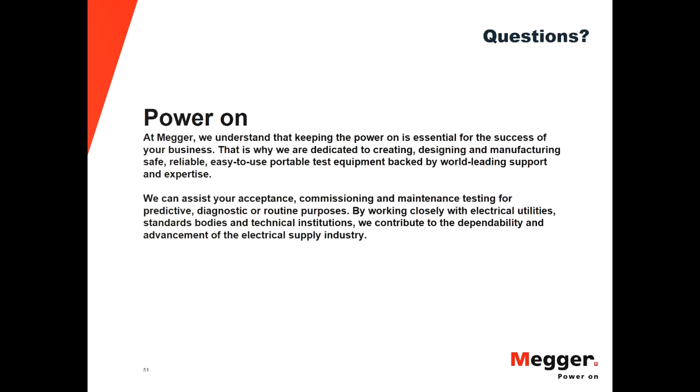Capacity testing requires a lot of effort and time. You need to have backup batteries in case you don't have one. You need to make arrangements for those to be able to do testing. On the other hand, impedance testing is easier to carry out. You don't need to take the battery off service. It's still online. You're just taking measurements on the battery bank. So impedance testing can be done more frequently at regular intervals in between capacity tests. Even when you're not doing a capacity test, you're still tracking the condition of the battery, and you still have some information in the intervals between capacity tests. So you can have both tests as part of your battery maintenance program.